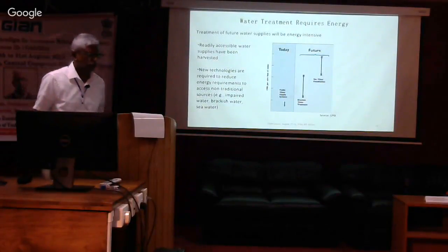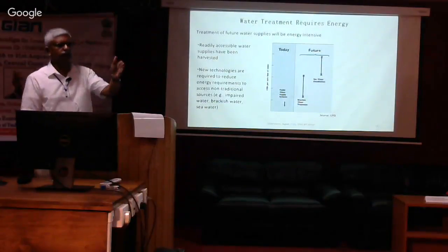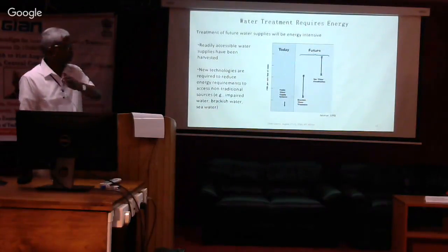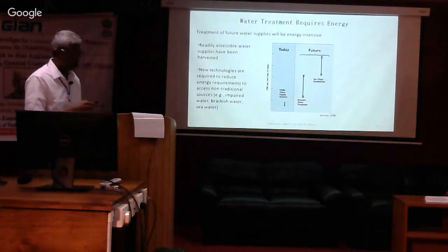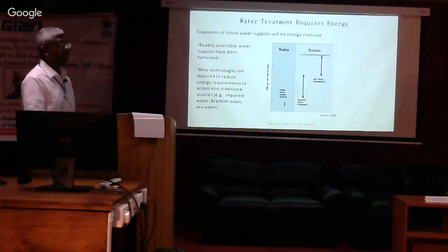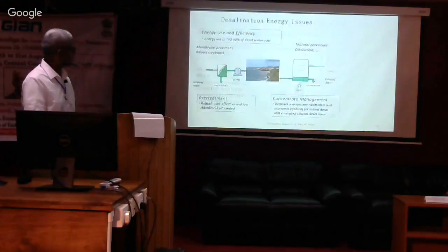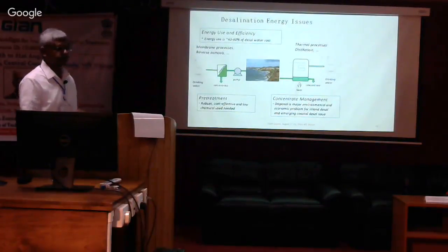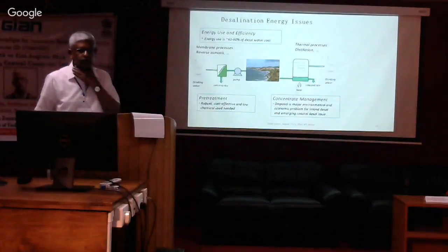If you look at a typical water supply scheme, as I said, coagulation, sedimentation, filtration, disinfection, they are not energy intensive. But if the quality of the water worsens, we go to brackish, if we go to sea, then energy use is much higher. Especially desalination, energy use is typically about half the cost of the water production.